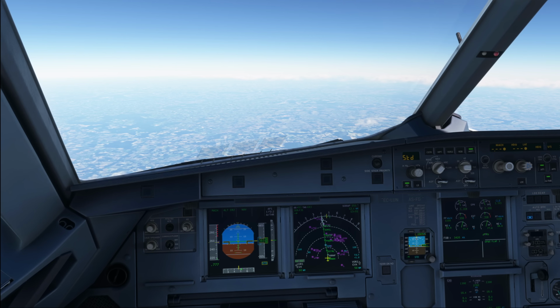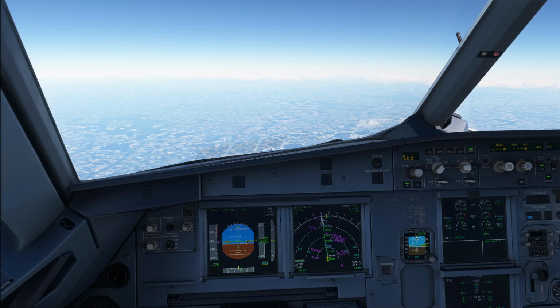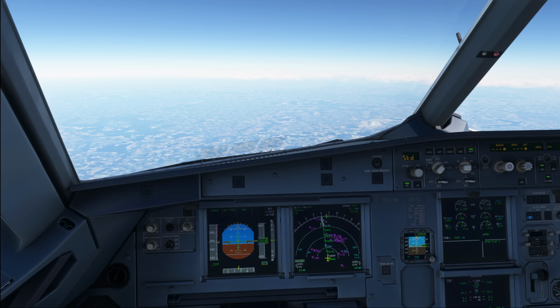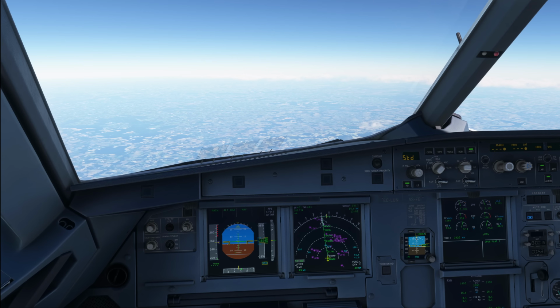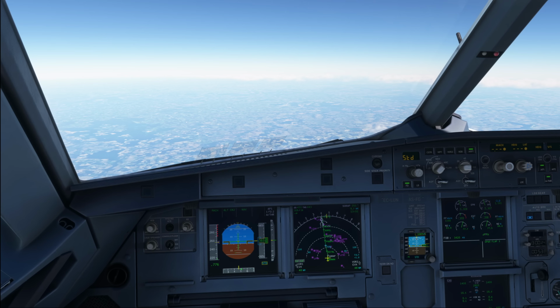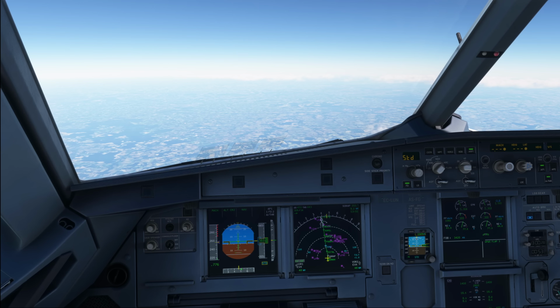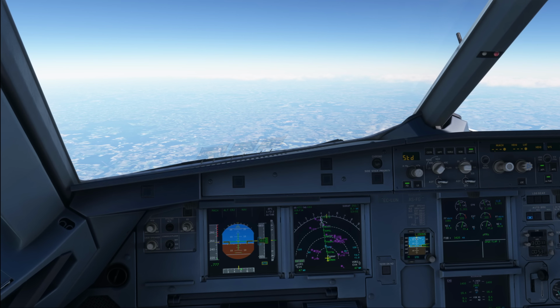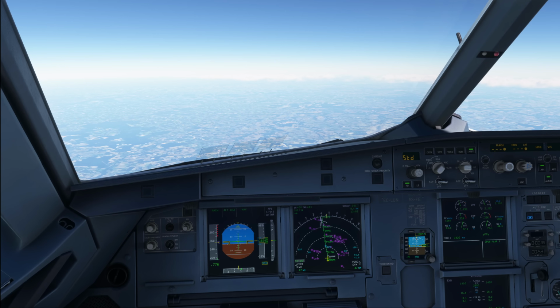Now, going on to the preliminary cockpit preparation, the flight crew may delay for as long as possible the APU start and use the ground electrical unit and ground pneumatic unit when available. Now, in terms of air conditioning, if one pack is sufficient to supply air when on the ground, the flight crew can select one pack to off. In such a case, the flight crew should switch between the packs on each flight in order to prevent excessive wear of one pack.